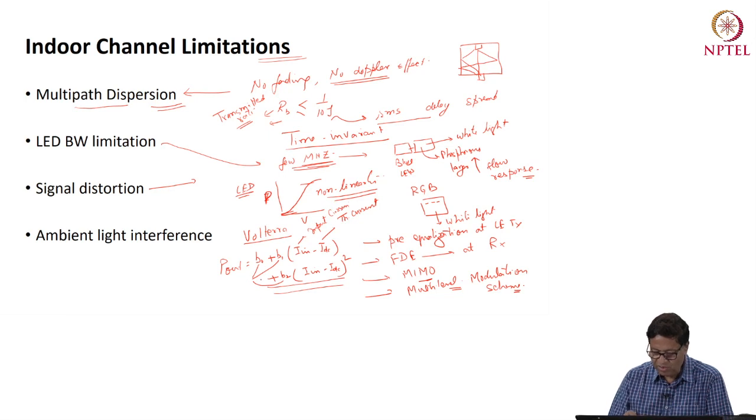This gives a good fit to handle this nonlinearity, and one can get some advantage in terms of performance and modulation. So this is one way of handling the signal distortion which comes because of the LED's nonlinearity and limited dynamic range.